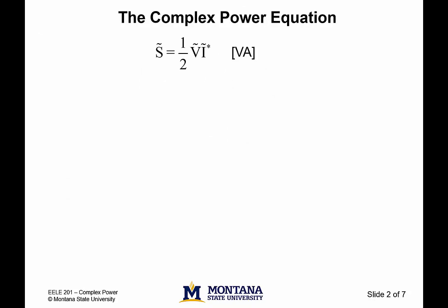Here again is the expression for calculating complex power. Let's manipulate the equation a bit to see what we may find. V phasor is just some amplitude, Vm, and an angle, theta v. We use the conjugate of the phasor current, and so we have what? Im angle minus theta I. The minus sign associated with theta I comes by virtue of the conjugate.